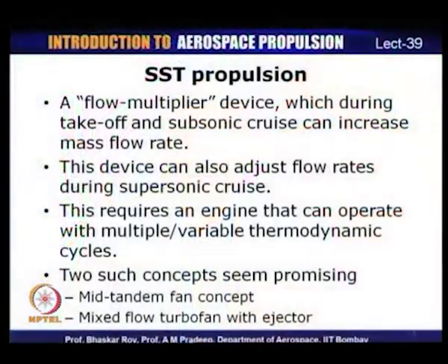So that in both modes, supersonic flight as well as subsonic flight, it satisfies the design requirements. There are different concepts which have been proposed over the years, and two of these concepts which seem promising and are being researched are the mid tandem fan concept and the mixed flow turbofan with ejector. Both these concepts try to satisfy the design requirements. Basically, they try to adjust the flow rates during supersonic cruise, and therefore the same engine operates in two different cycles. One would be an engine without bypass or a very low bypass, and in the other mode it operates with very high bypass. So, which is why it is in some sense a variable cycle engine.